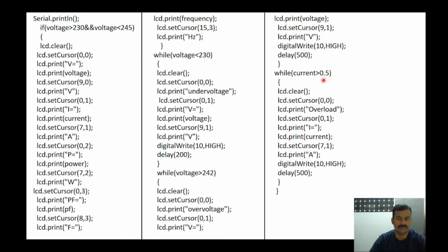If you are implementing this project in real time, there is no need for a transformer, because you are not going to simulate. You are going to protect your load from the actual load variations or actual supply variations. So you need not have a transformer. That time you don't have any limitations. This energy sensor can measure up to 100 amperes of current. So you can use this project for a whole house. If it is a medium to small size house, you can use this particular project for protecting your house or your shop